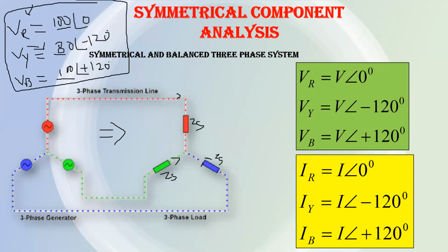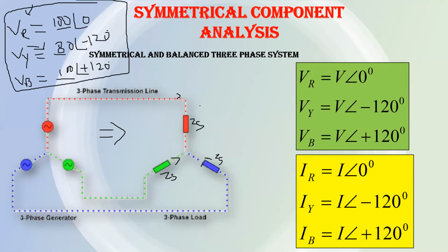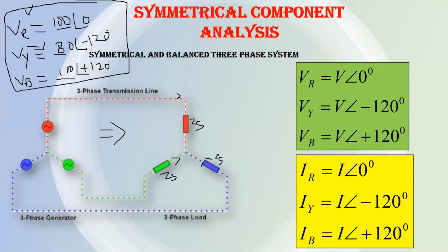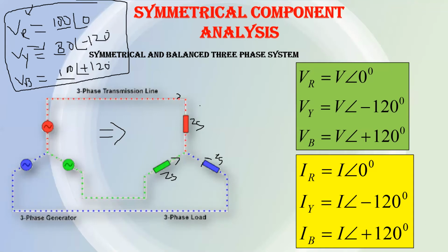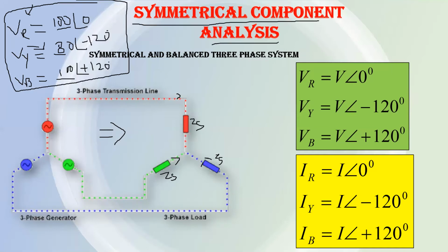And if phase current differs from another phase, then obviously power will also differ from the other phase power. So you cannot analyze a power system on a per phase basis if your system is unbalanced, if the supply is unbalanced. So there is a need for a technique through which you can analyze an unbalanced power system on a per phase basis, and that technique is symmetrical component analysis.